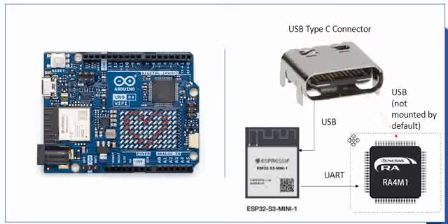There is actually a USB switch on the board, an analog switch basically, which helps to switch between USB of RA4M1 or USB of the Espressif module, so that you can control it by using one of the GPIOs which is connected.